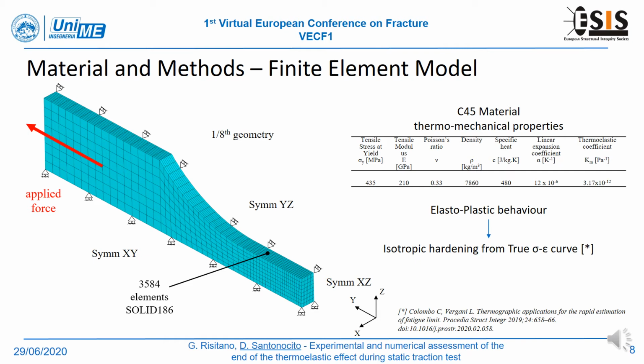Symmetric boundary conditions were applied to the geometry, while the tensile force was equally distributed on the grip section nodes. The first stress invariant and the plastic work per unit of volume of the cross-section area have been evaluated during the load increment.